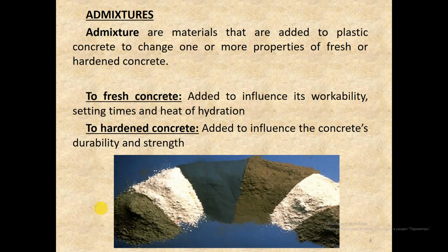In plain concrete not containing any embedded metal, chloride-based admixture may be used when early rapid hardening is required, in which case a dosage rate of 1.5% anhydrous calcium chloride by weight of the cement will usually be sufficient.